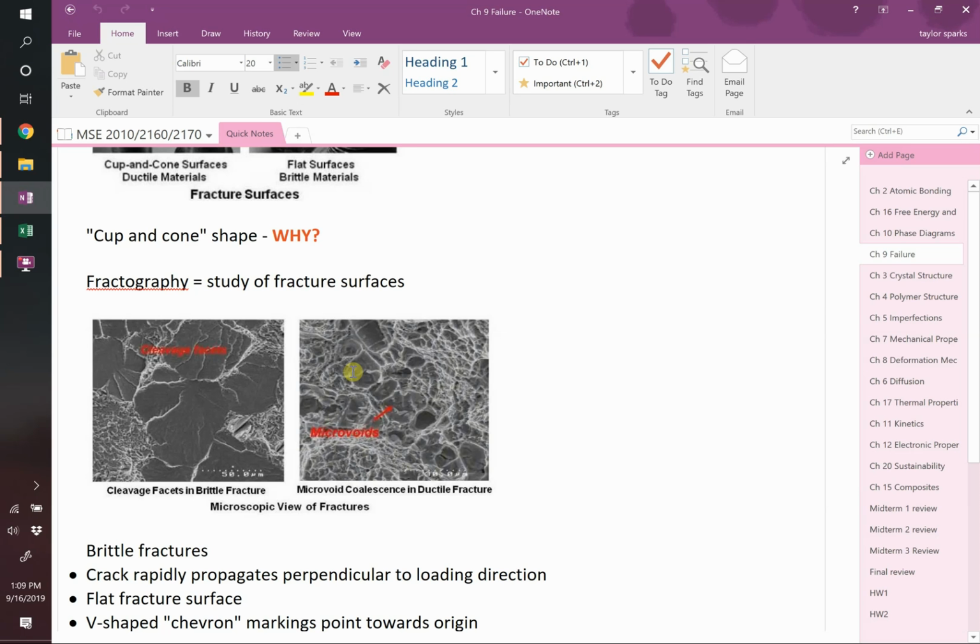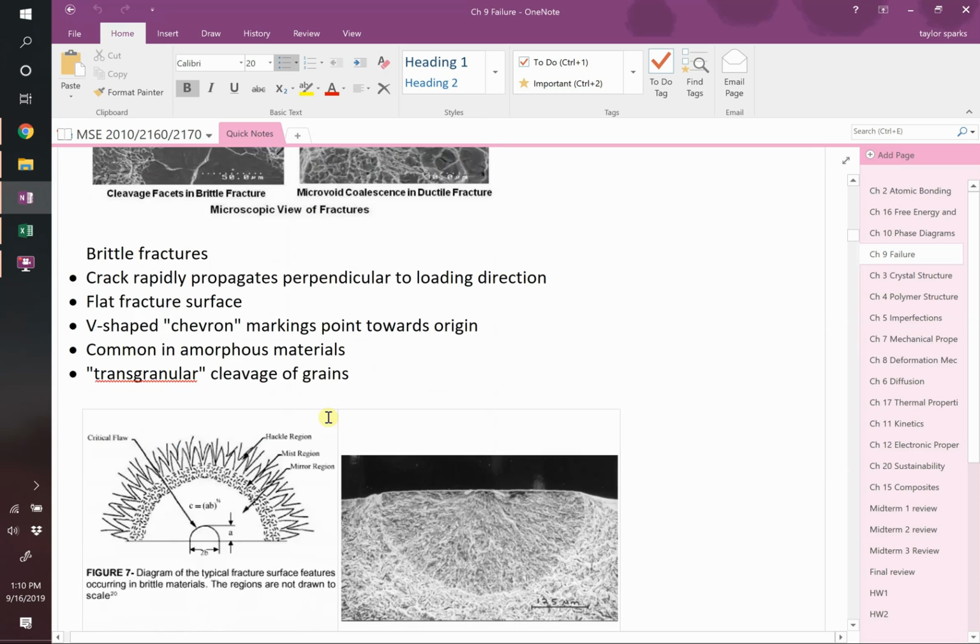If you looked at it under a microscope and you saw the two following images, one of the hallmarks of brittle versus ductile fracture is the same thing we saw in the banana at a macro scale. If it's a really ductile material, ductile's over here, you'll see lots of deformation regions where the crack sort of meandered around portions of it, highs and lows, whereas a brittle material looks kind of mirror, right? Like very flat and glossy like that. The reason being, we'll get to in a minute, has to do with how the crack propagates, okay?